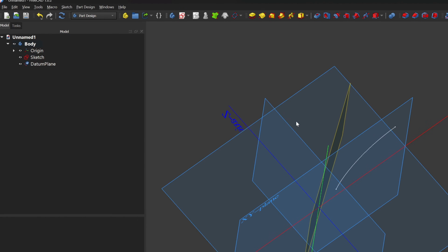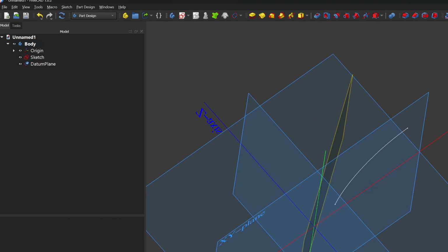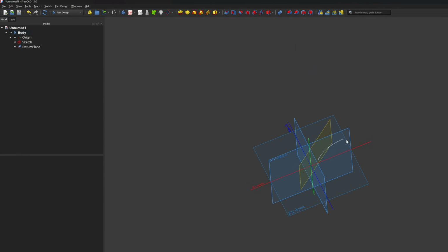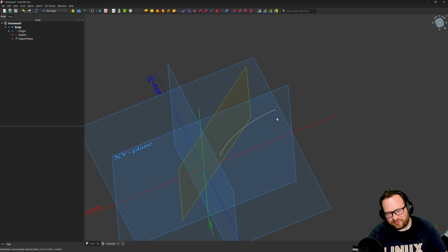So we're going to make a 5-spoke wheel, and 360 divided by 5 is going to be 72. 72 divided by 2 is 36. So we're saying we're going half of the spoke around. That's how I got that 36. So we're going to make, as far as one spoke is concerned, half of our hub, and we can mirror that later. So I've created my 36 degree datum plane, and I'd like to make my next sketch.